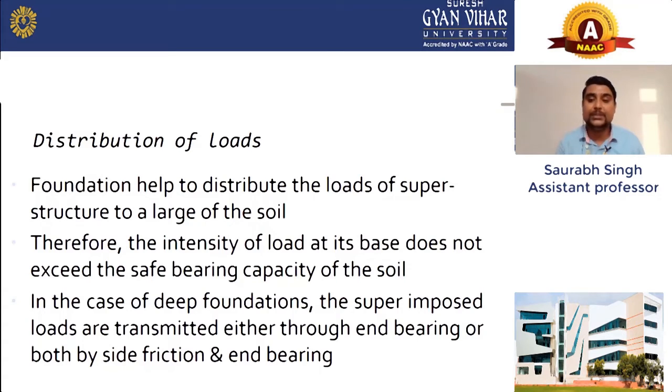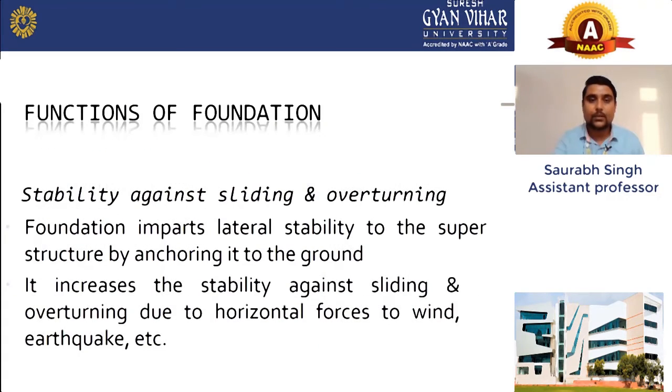Therefore, the intensity of load at its base does not exceed the safe bearing capacity of soil. There is also a third point. In the case of deep foundation, the superimposed loads are transmitted either through end bearing or by both side friction and end bearing. This is the function of distribution of load.